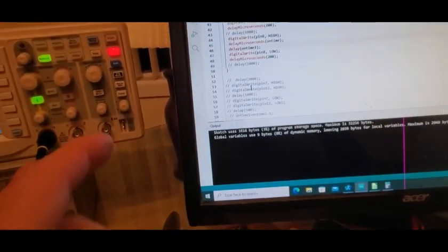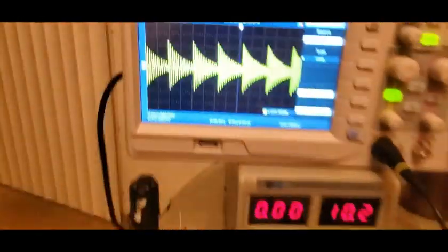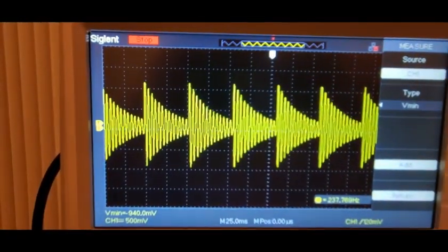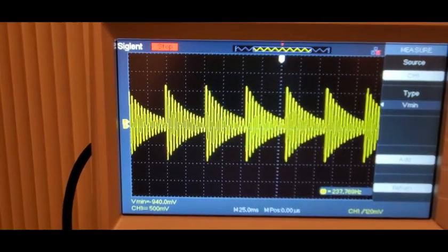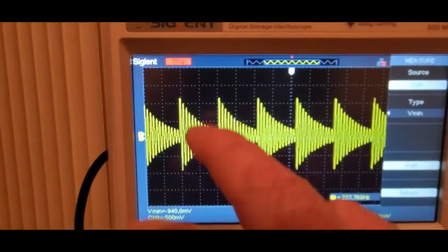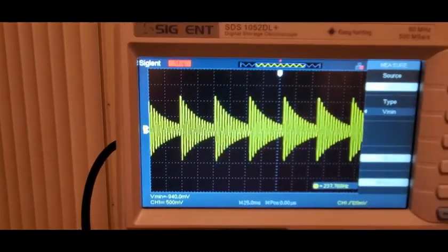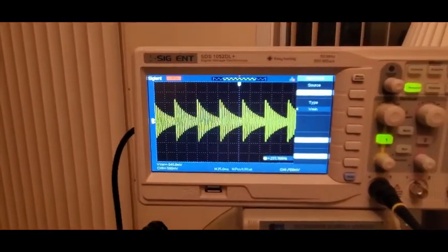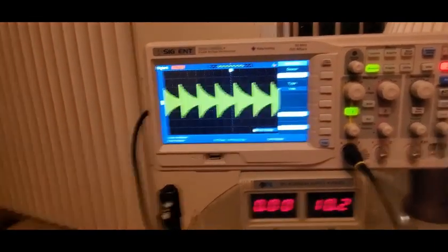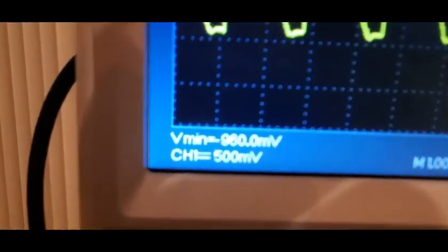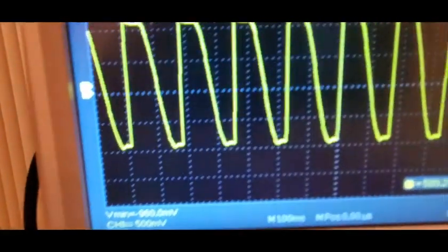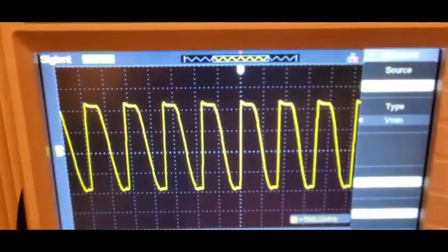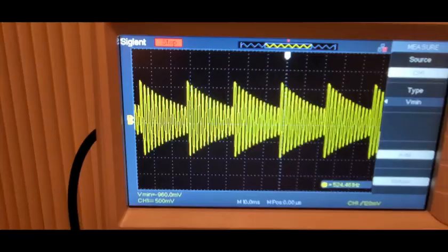So again, each time I'm letting the cap just ring 12 times, and now it looks like that. So that's a lot less undamped than before, isn't it? And that's because we went from 10 down to 9.4. So now instead of a 4.7, let's go to a 1 UF cap. So I've gone to a 1 UF cap, and now we see it goes from 10 to -9.6.